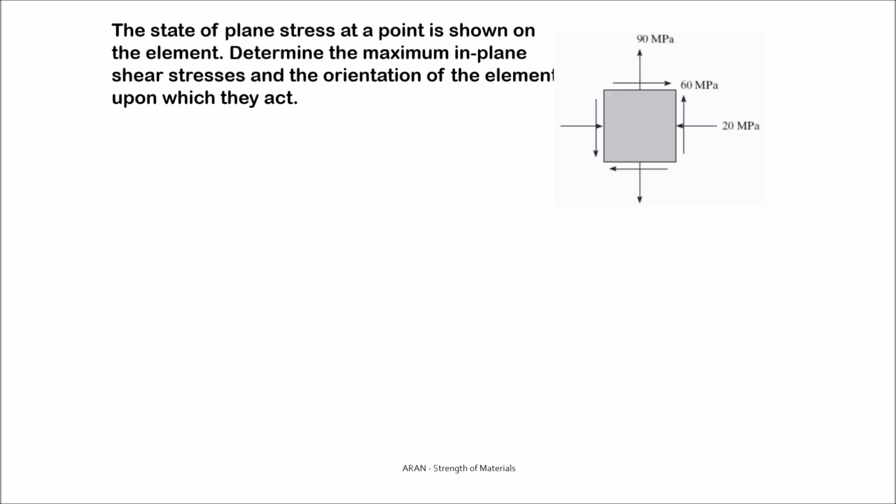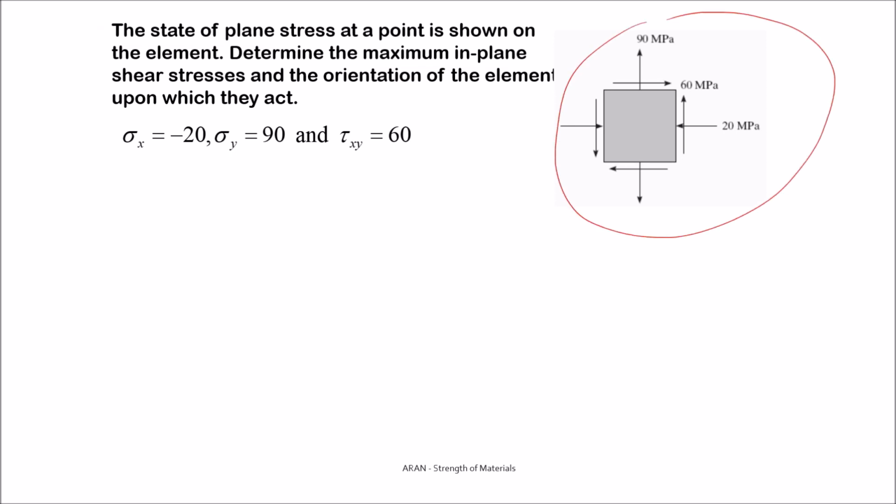A simple problem. For a point, the stress state is given. It's a two-dimensional case. Determine the maximum in-plane shear stresses and their orientations. First, we write down the components, sigma x, sigma y, and tau xy.